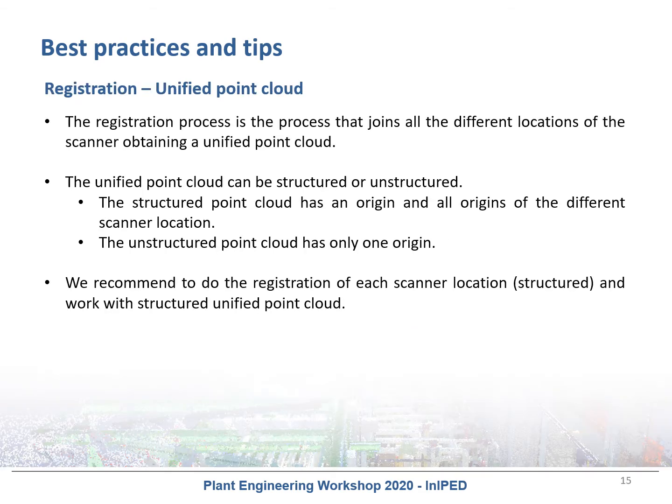In a previous slide, we saw what the registration process implies. I just want to point out that it's important to work with a structured unified point cloud. Remember, the unified point cloud has to be located in the project coordinates. In plans, it's important to know where the north of the plan is defined, and sometimes there is a difference between the plan north and the geographical north.